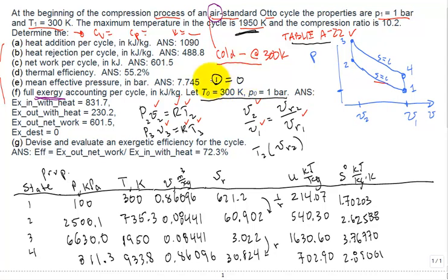I don't know if I'm writing that well, but the pressure at state 1 and the dead state temperature are the same. So it's just make that comparison. So what we can do is say, what is the change in S naught from the dead state S? Now, let me back up. If I wanted to, I'd say, what is S at state 1 minus S naught, the dead state? Well, that would be S1 naught minus S naught.